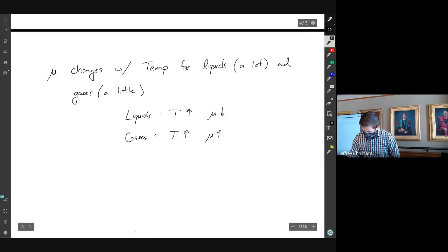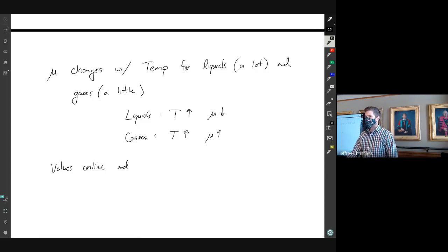So there are values. If you need to find the viscosity of water, if it's not given to you, people have measured these. There are ways that you personally could measure them. I did some work in undergrad with oils and different stuff for calibrating fuel injectors for cars. So we had to make sure that our mixture was the same viscosity and density as gasoline. There are little viscometers that you can use to measure what the viscosity is. So it's something you can measure. It's something also you can look up really easily.